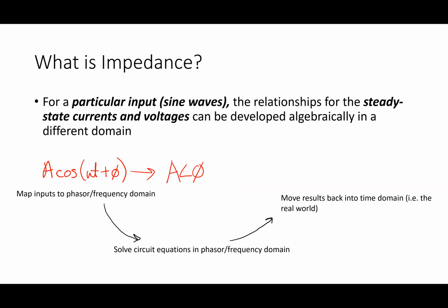The implication when I do this is I have to map the whole circuit. I do the circuit equation in the phasor frequency domain, which means I need to derive impedances Z sub C and Z sub L. This was a key takeaway from the test, which I tried to give a hint on Wednesday was going to be there. What do Z sub C and Z sub L require? They're only true at one what?